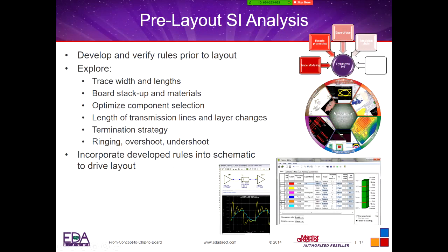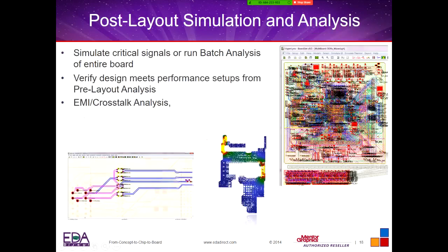We can come into the layer structure and set up our layer structure in here: the board stackup, thickness, pre-preg, what materials we want to use, impedance control layers. So we have full control over our layup and everything that we want to do inside of the SI tools.